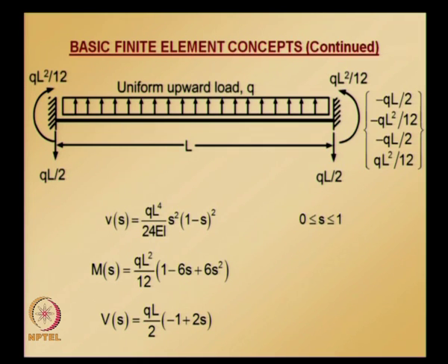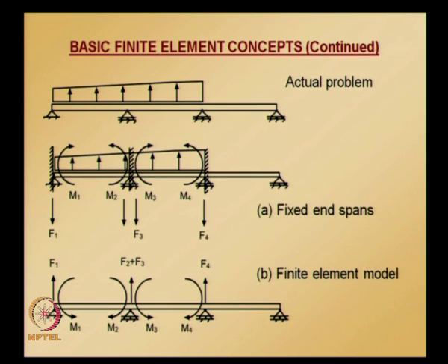So, the actual problem, irrespective of the boundary conditions, what we will do is we will assume each span to be fixed, and we get these fixed end moments, which I just showed you for a fixed end beam subjected to uniform upward load.